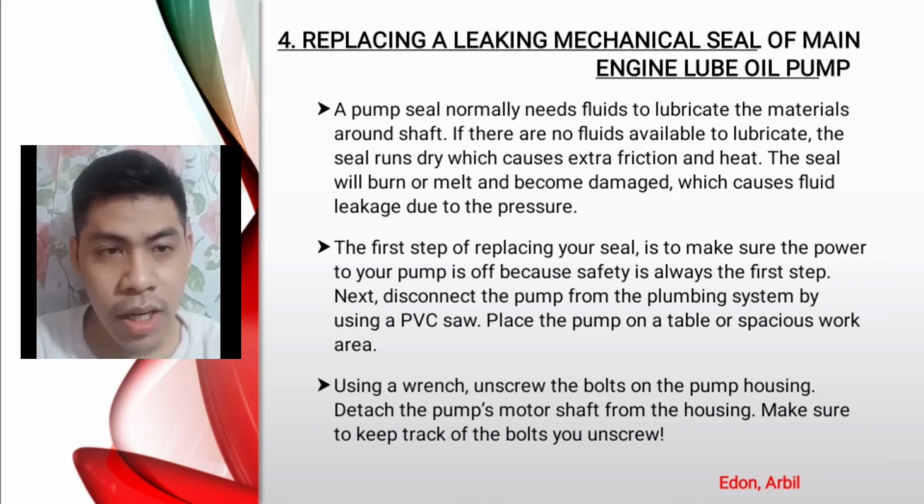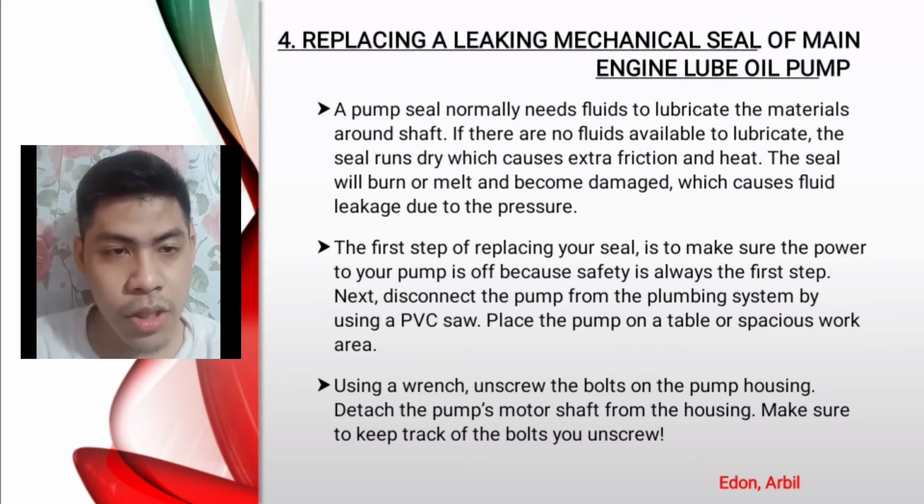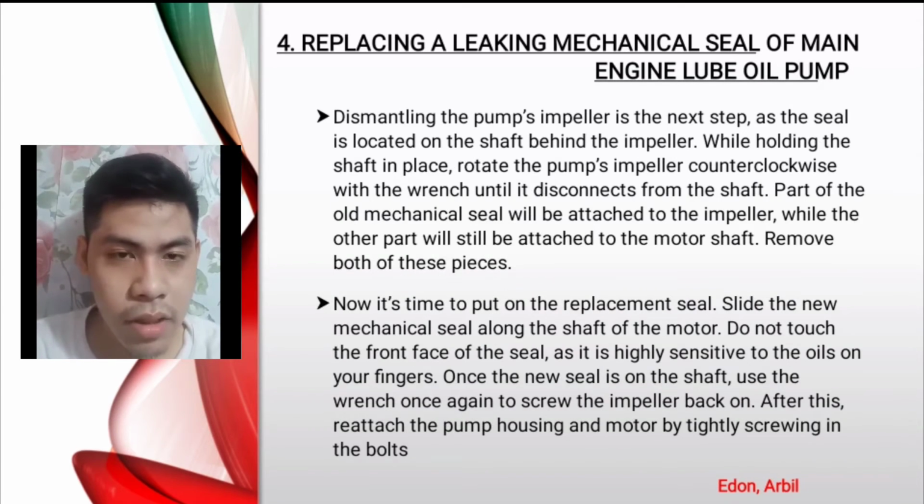Second, using a wrench, unscrew the bolts on the pump housing. Detach the pump's motor shaft from the housing. Make sure to keep track of the bolts you unscrew. And third is dismantling the pump.